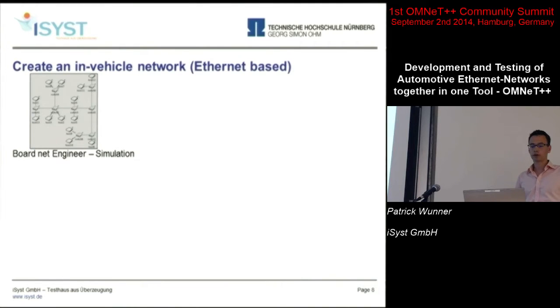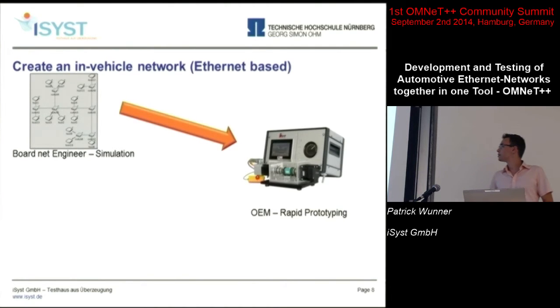When the network is built up, then the boardnet engineer defines the data in a network description file such as FIBEX or ARXML, and provides this to the original equipment manufacturer, who has to program the ECU for the boardnet.